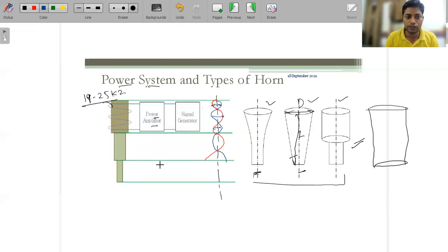Because what we have to do is connect the tool over here. So this is the amplitude that we are getting over here. This is the maximum amplitude that we are getting, but as you connect the horn, this amplitude increases. That's why we are using the horn. And this is not random; it is by experiment only, after the experiment, that we concluded we can use the horn.